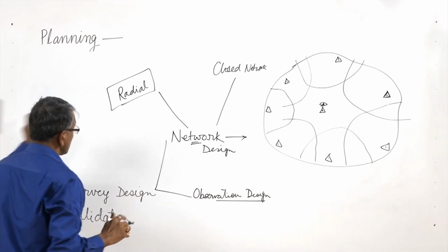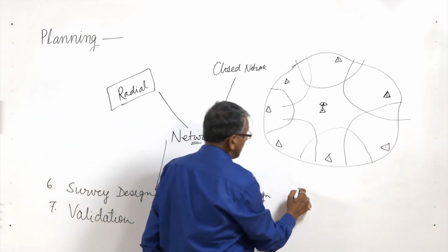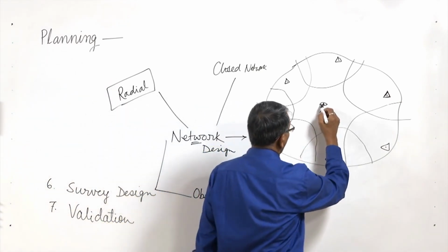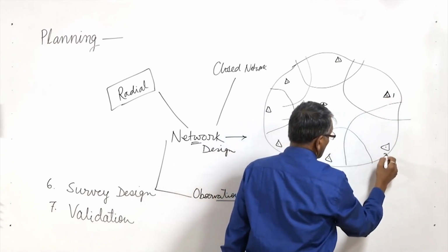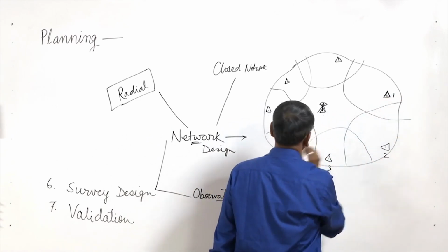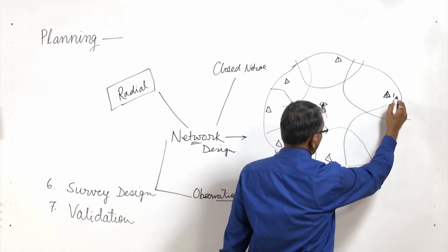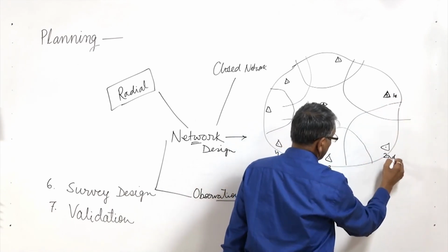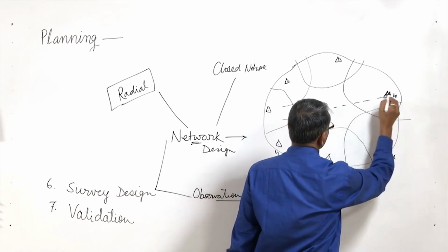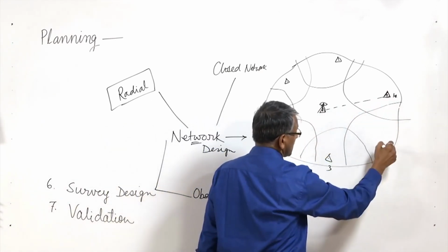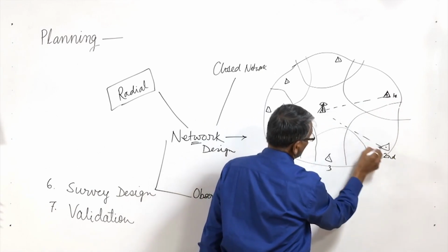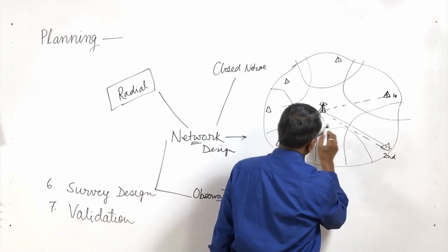So one of the methods is the radial method. Suppose we have 2 receivers. Then only one will always be placed here, and the other will be placed first at station 1, and I will take the reading between these two. After some time I will shift it to the next station and take the reading between these two; this is the baseline.